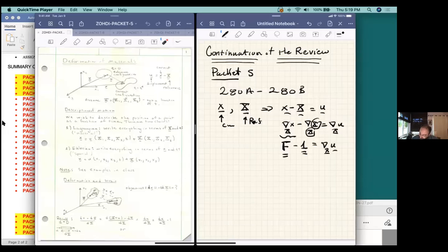And from there, everything goes forward. We start to develop all kinds of different measures of stress and strain. Of course, the one that's most important to us is the Green-Lagrange strain. And the Green-Lagrange strain is 1/2 F^T F minus 1. And that, of course, is a strain measure that collapses to the classical small strains measure, which is the one